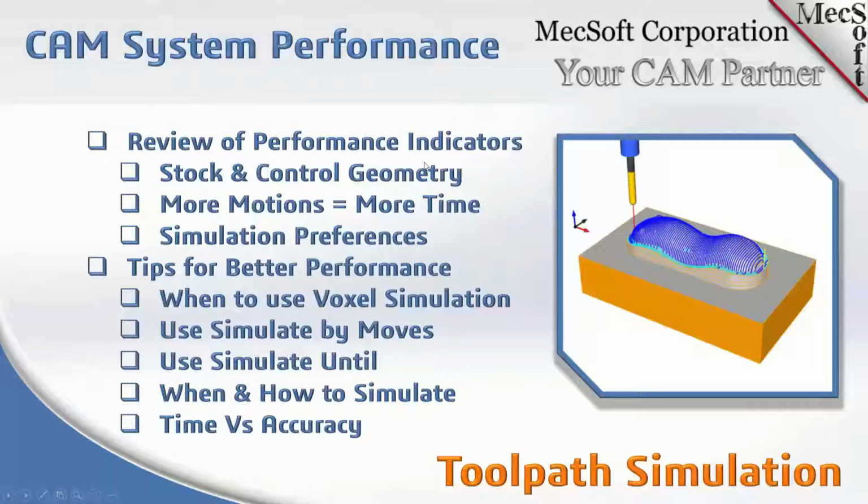What are the performance indicators for simulation? Obviously, it's your geometry, the stock model, the size of your stock, your control geometry, your containment area. How large of an area are you cutting or are you simulating? You can think of it simply as more motions, more time. The more times that tool moves from point A to point B, the more time it takes to simulate. But there's a way around that, and we're going to show you that trick in a minute. Simulation preferences obviously also play a major role in how fast you can get through a simulation.